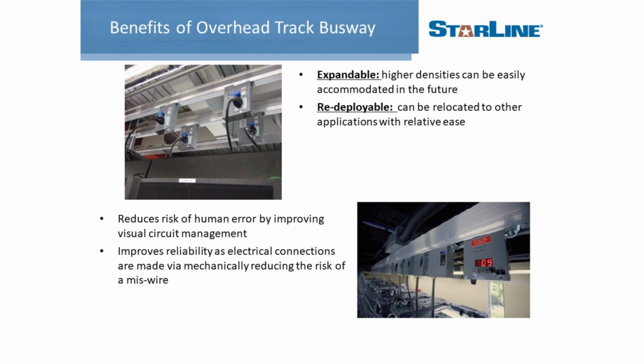We talked about the reduction of human risk. The nice thing about this too, typically the bus plugs are installed directly over the cabinets. So you have a very easily visual scenario. If I need to do work within this cabinet, I know I'm shutting the breaker off for the cabinet directly below where I'm doing the work. So just any time that you can reduce that potential risk of human error is definitely beneficial as well.